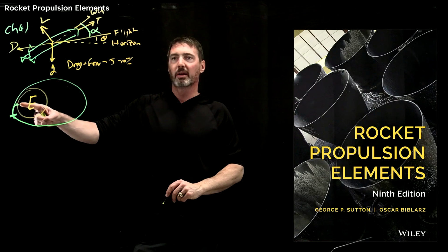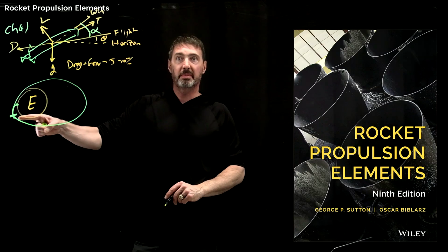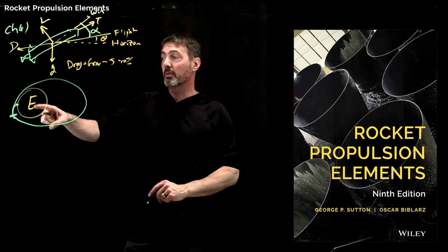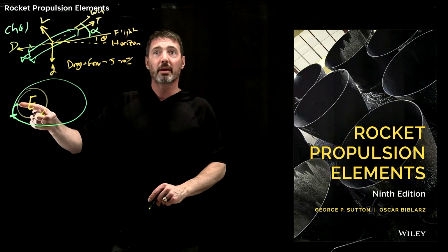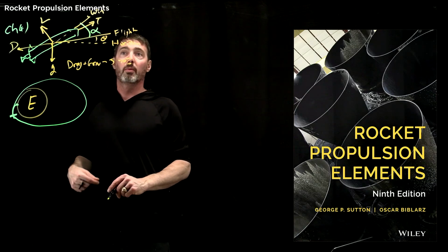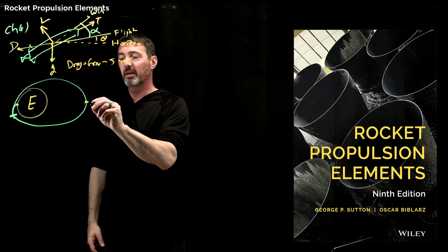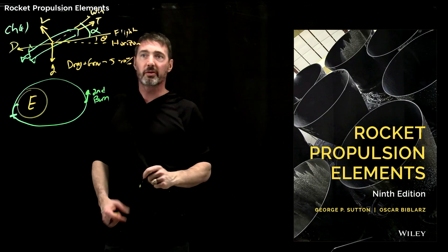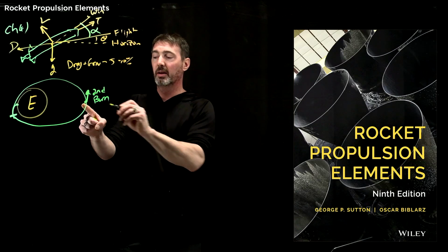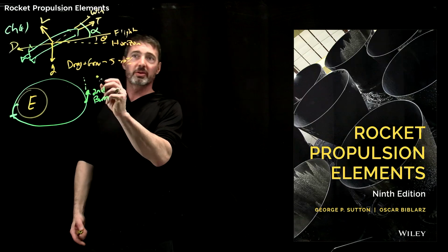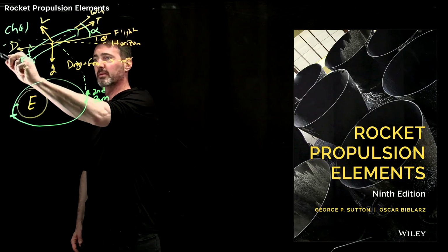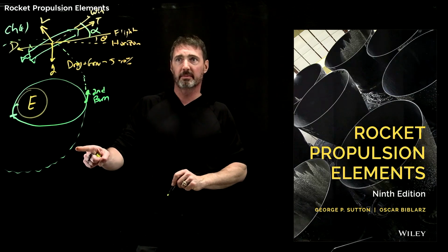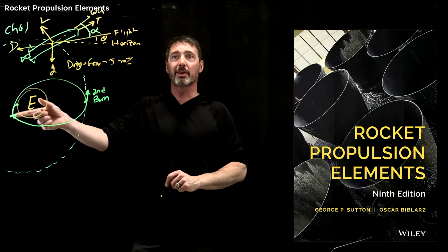So what happens at low Earth orbit at these speeds, 5 miles per second, an orbit is about 90 minutes. What's going to happen in 90 minutes if you don't do anything is your rocket is going to re-enter the atmosphere. So what you have to be able to do is, 45 minutes later at the apogee, you actually have to have a second burn. This is called a circularization burn. You have to get up to here, add more energy, and apologies, I'm going to end up going over my nice beautiful diagram. This is how you then circularize, and now you're in low Earth orbit again, not to scale.